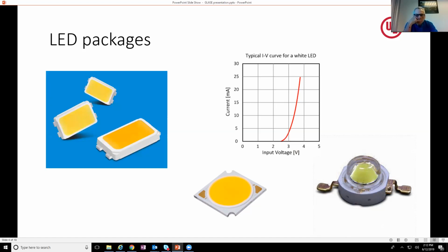Your basic laptop also has a power supply where it converts one type of branch circuit supply to a certain voltage and current, but your laptop works on a constant voltage concept. LED packages require constant current.